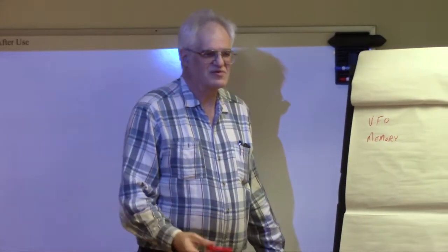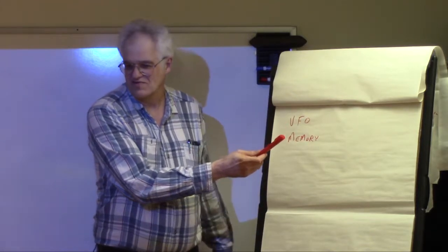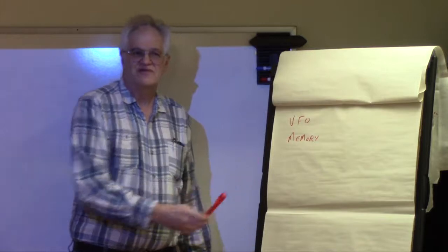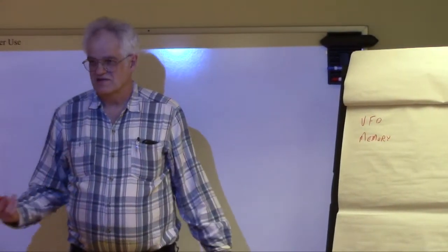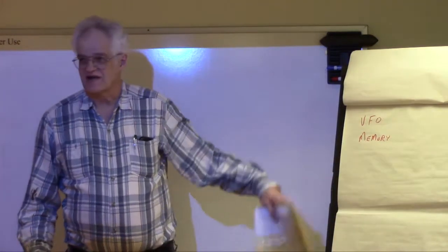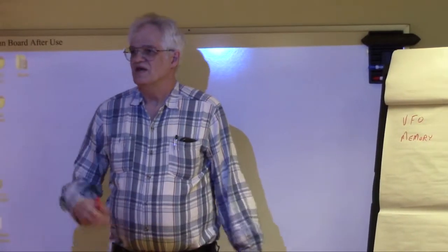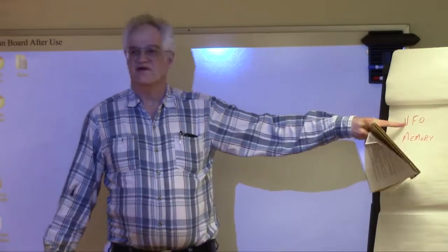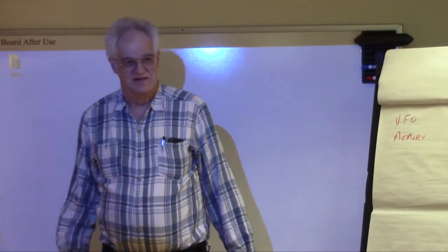Nowadays, typical radios still have VFO, because the term is a carryover from years gone by, or memory mode, where you have a bunch of memories that you've pre-programmed with the frequencies you're going to use. So it's just a matter of selecting a memory that's got the frequency that you want to use. If it's a frequency you don't have in your radio, you go to VFO mode and just dial it up for the frequency that you want.